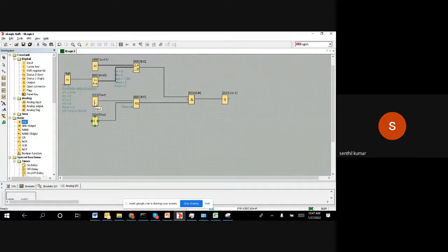Now once I start, I'm going to open valve one, and while the valve is open, slowly the liquid will come down, and this comparator is going to monitor this tank level. If the tank level goes less than 500, so 500 minus 500 is zero, immediately it becomes on, and when it becomes on, we stop it. So now we understand that once this comes, we are stopping it.